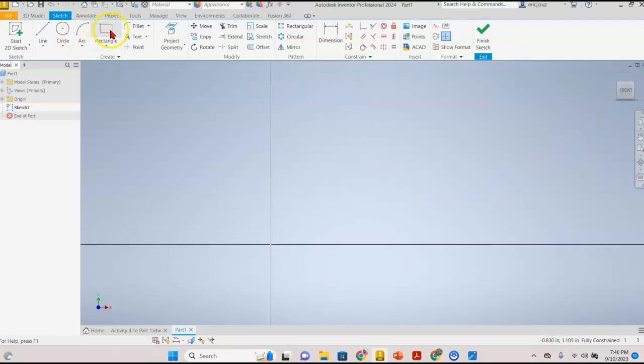What we're going to do then is click on rectangle and move our mouse to the origin here, and it should snap. Click, and then move your mouse to the top right. Notice this: if I press tab on my keyboard, go ahead and press tab on your keyboard and you'll see it highlights those text boxes where we could put information in.